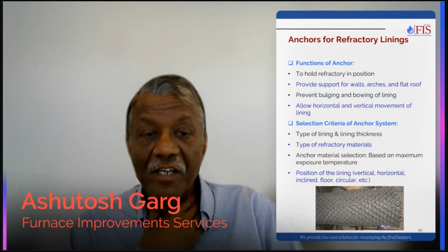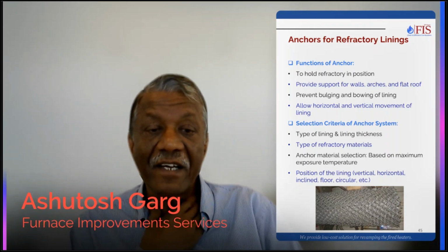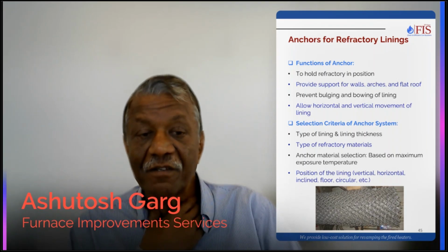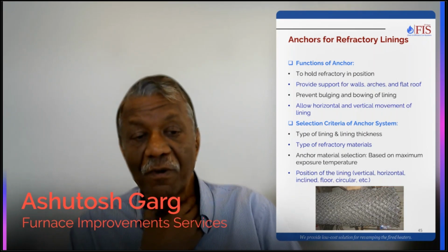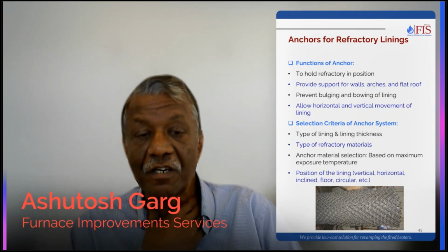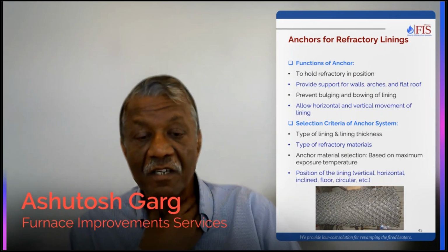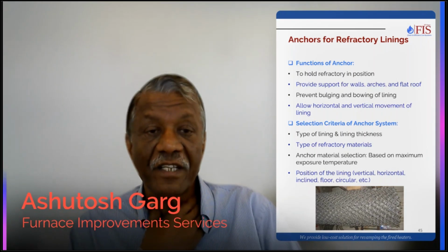So anchoring depends on the type of lining and lining thickness, type of refractory material, anchor materials selection, and where you are applying the lining. Are you applying it at vertical, horizontal, roof, inclined, etc.? So that kind of dictates how you will be putting the anchors.